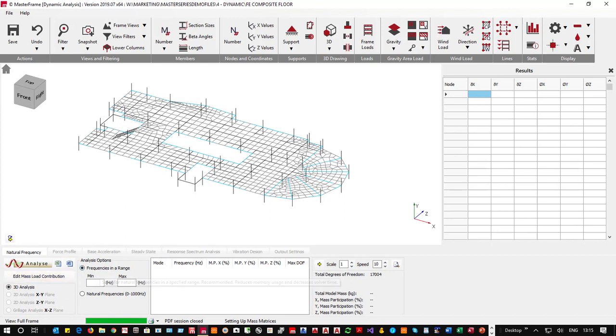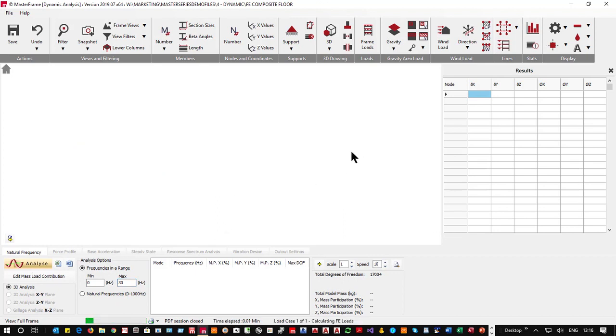Frequencies. Now the frequencies we need to consider are quite a lot. We need to consider everything up to 8, and then we need to look at the fourth harmonic of that, so we're moving up to around 30. So if I say from 0, in here, to 30, or even 32 if you want to be more exact, but it's not an exact science, we can then consider that. And I am now going to ask it to process this, and I'm just going to go analyze. And this will take quite a wee bit of time. It's going to take a minute or two.